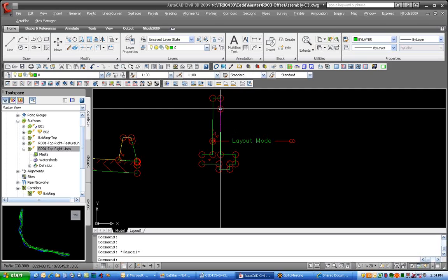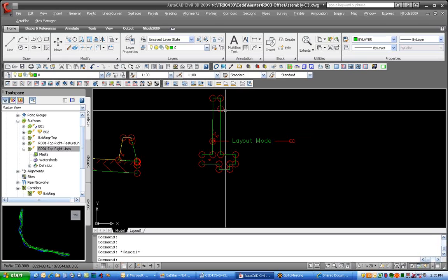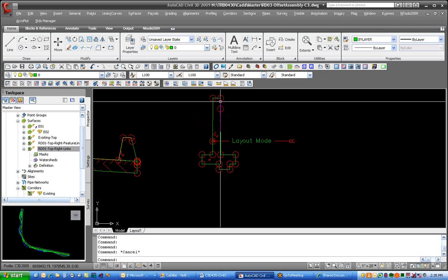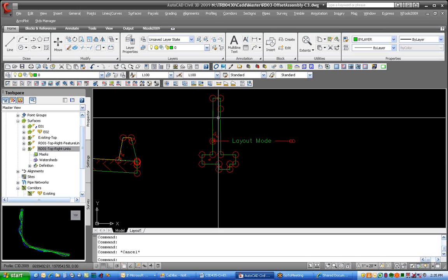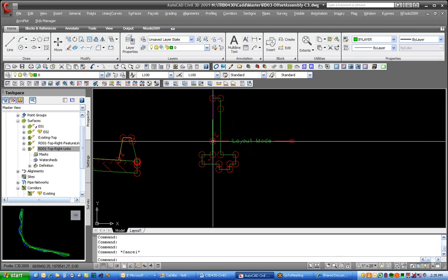And it's just like, why go through all that? So the one I built, you can link this to a profile, or this I attached to that link offset. So this is the connection point, or what they call the hook point. Then there's a profile that controls this point here. You can specify the height here, you can specify the depth here, and then the wall will actually flip if this point goes below that point. The wall will flip over to the other side.